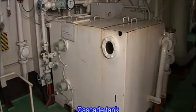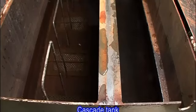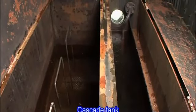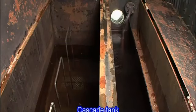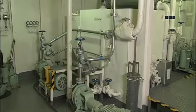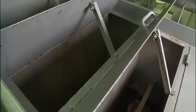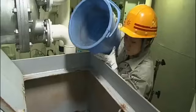This is a cascade tank. It is used to separate and remove oil content, filter out corrosion products, and store feed water. For auxiliary boilers, a cleaner may be injected into the cascade tank and then sent to the boiler unit.